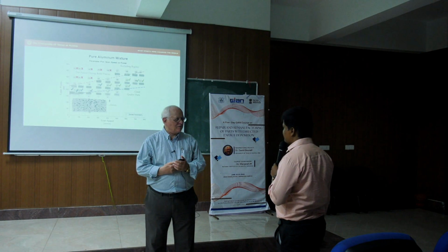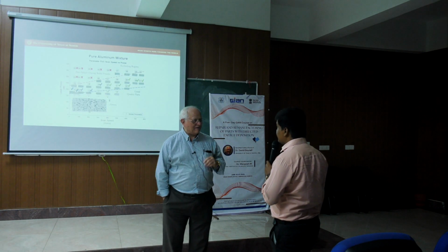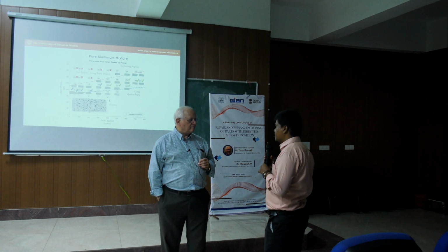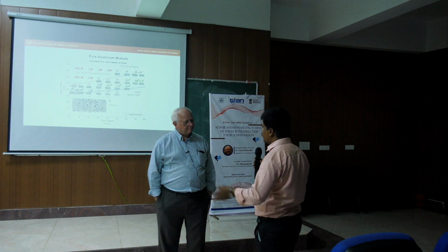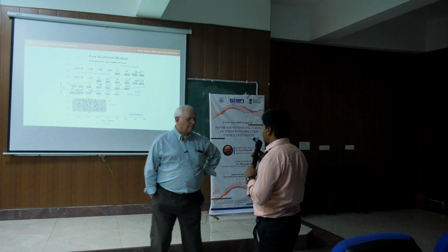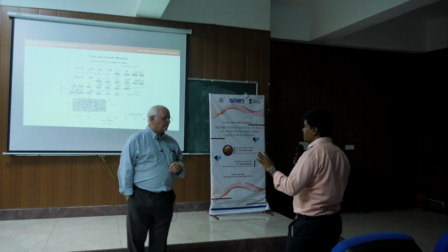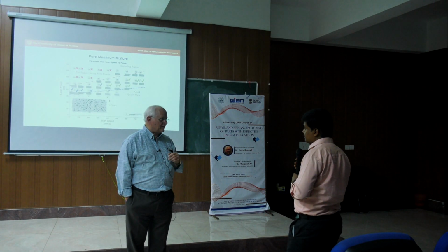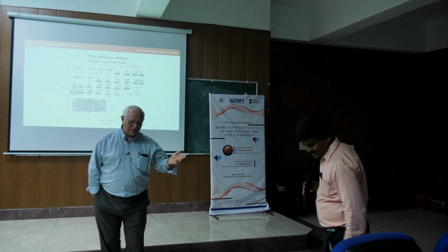Okay, my echo's not doing any better. Let me try one more time. Different directions in the building. Yes, we are getting different mechanical properties, slight variations with respect to X, Y, or Z. But if they use optimal process conditions, controlling the printing environment and minimizing the defects, are they going to get uniform, isotropic properties? So the anisotropic effects: can we minimize or eliminate those? Yes, that's the question. Thank you, and sorry for the delay.